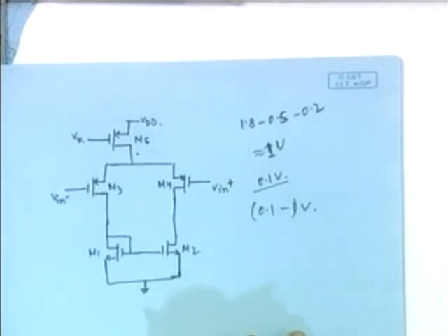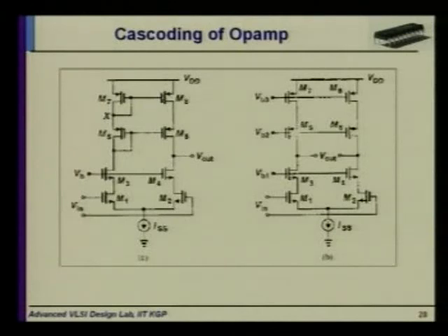So in this case also, if we want to sense a voltage near about 1.2 to 1.3, we can do that. So the option is that we can use both of these structures, NMOS and PMOS, together. That is called folded cascode. This is not in the scope of this discussion, so we are leaving that.